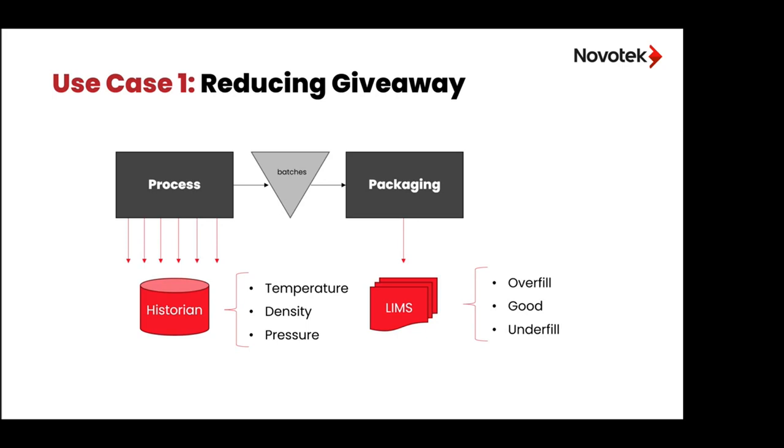In this example, we'll look at batches coming out of a process. During that process, a time series database is recorded in a historian with several values, temperature, density, and pressure, which at the end might influence the percentage of giveaway of each batch on the packaging lines. Those giveaway percentages have been recorded in a separate LIMS system and, as you will see in the demonstration, are then identified as an overfill, a too-much product, a good product, or an underfill product.